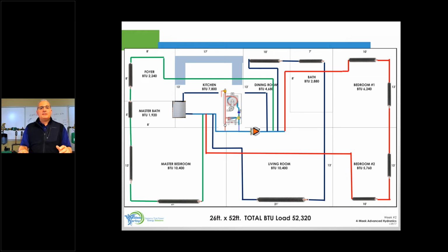Yeah. Please understand, we're the TACO reps. We made circulators here that are really small and circulators that are the size of a small pony. If you want to put 100 GPM through a piece of half-inch pipe, we could do it. But they'll hear it from here to Newark. All right. We don't want to do that. That's why that 4 feet per second is safe. As you heard John say, the lowest number would be really 2 feet per second. And John will go into more detail on that when we do week 3, when it talks about getting air out of the system.